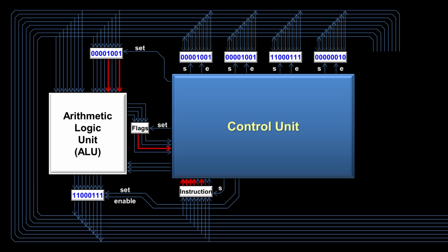Anytime there is more than one possible path through a program, the computer is using these instructions to tell it which way to go. So now that we're finished with the compare instruction and our flags are saved in the flags register, we need to tell RAM that we're ready for the next piece of data, in this case the next instruction. So inside the CPU, another register that is very important is what's called the instruction address register. The CPU uses this register to know where the next instruction should come from in RAM.